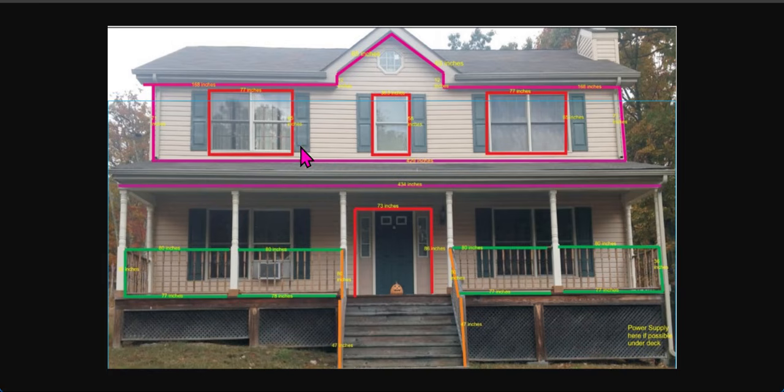Now, I will say an important note, do not start your strings in the middle of a window or door. Don't start them up here in the middle. Don't start them here and then try to go around. Always start them at a corner. And in particular, xLights loves this left corner, but you can switch them to the right corner or the upper corner. But don't start them here and try to go around. xLights does not like that. And xLights will have a window option. It'll say how many pixels across, how many pixels up, and it'll be able to draw that. All right, so 25 feet is the number from where you mount your box to where your pixels are.